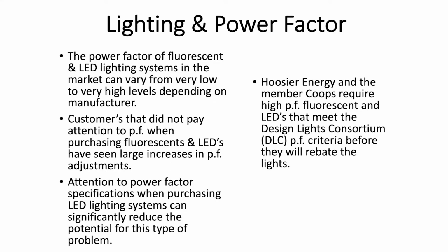LED lighting systems can vary from really low to very high levels depending on manufacturer. Customers that don't pay attention to power factor when purchasing fluorescents and LEDs have seen large increases in their power factor adjustment. Believe you me, they're not very happy when they say, "What? The utility gave us money to reduce our kilowatt hours, but now our power factor adjustment went way up? Nobody told us about that." So attention to power factor specs when purchasing LED lighting systems can significantly reduce the potential for having low power factor in a plant.